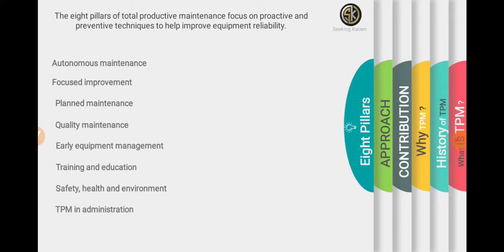Now here I have mentioned what exactly quality maintenance is, but how can this be achieved? This is done with the help of a concept called root cause analysis. Okay, so RCA is a systematic process for identifying root causes of any particular problems, and we can do this with the help of 5 whys. So what do I mean by saying simply 5 whys?